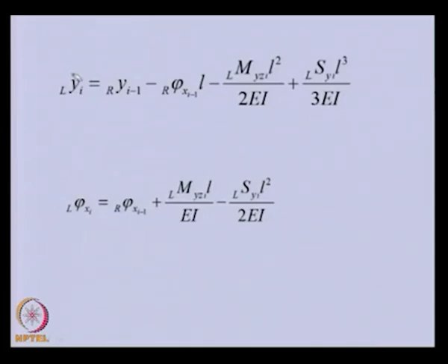The displacement of the left of the ith disk is given by these two terms, which come from the cantilever when we consider the shaft as fixed. From a strength of materials book we can get these relations: when a shear force is acting, what the linear displacement is, and when there is a bending moment, what the displacement of the free end of the shaft will be. Because we are dealing with a linear system, they can be combined.